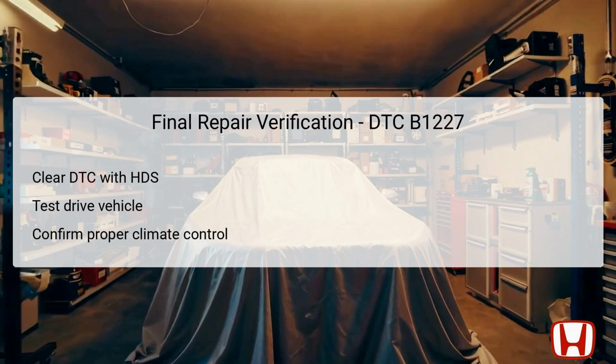After completing repairs related to DTC B1227, it's essential to verify that everything is functioning as intended. Begin by clearing the DTC using the HDS. This action will reset the system and allow for accurate monitoring of whether the issue has been resolved. Next, conduct a test drive and observe the vehicle's climate control performance to ensure that it responds correctly to changes in the outside air temperature.